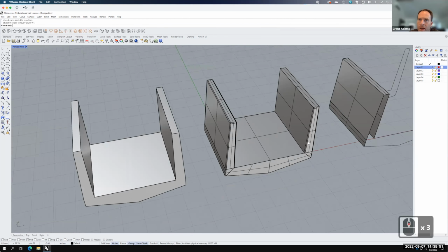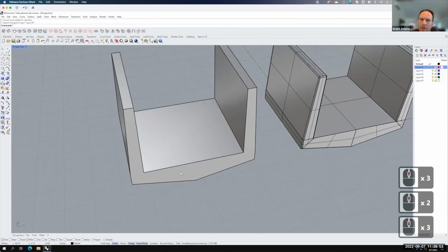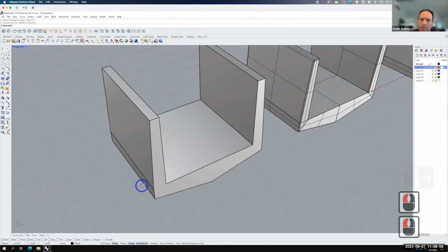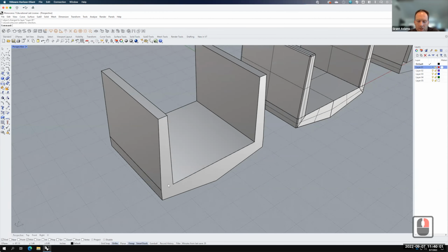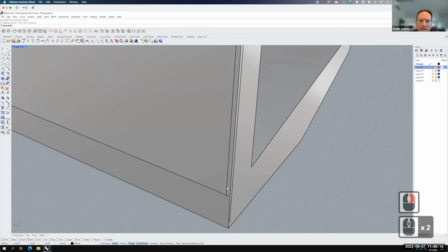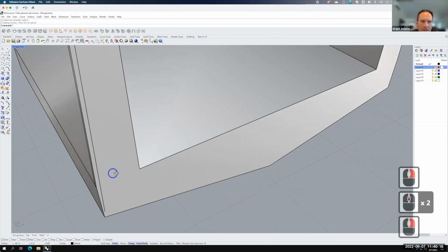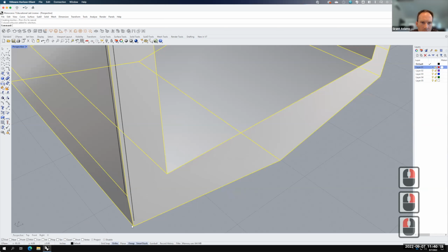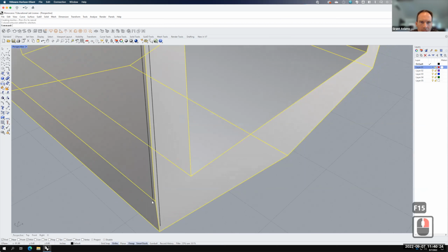So obviously I was working my way around that, but let's come back to this object. Remember, I created this object using an extrude. This one's going to present a problem potentially with how the chamfers work. So let's try it. Chamfer surface. And I'll do those two surfaces together. See how, because this is a continuous surface, when I do the chamfer, it makes this funky little extension because this edge of the surface comes all the way down here, but this surface ends at that kink. So my chamfer ends up being awkward at this corner.